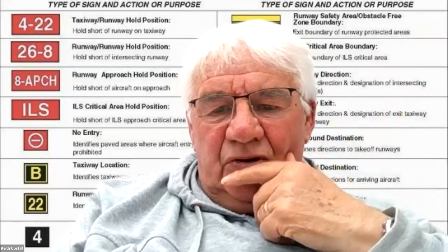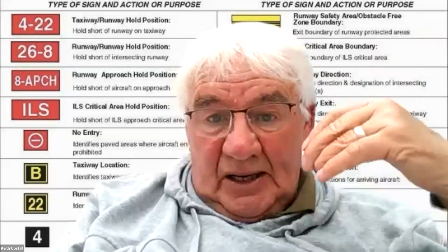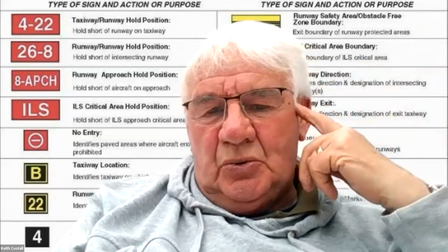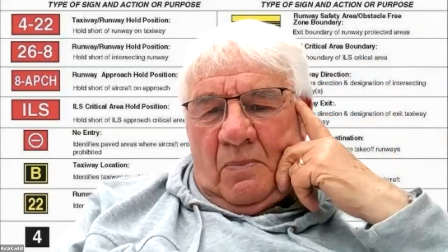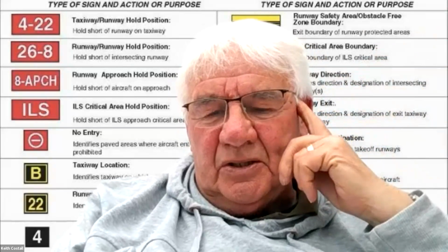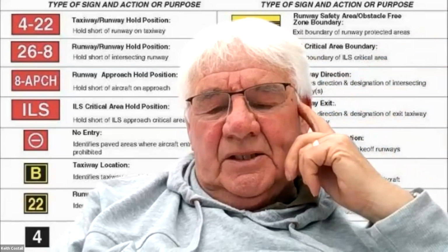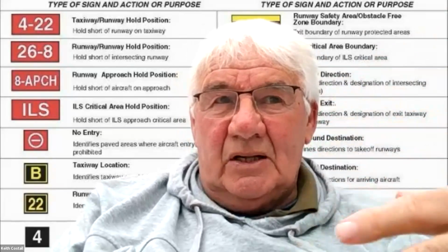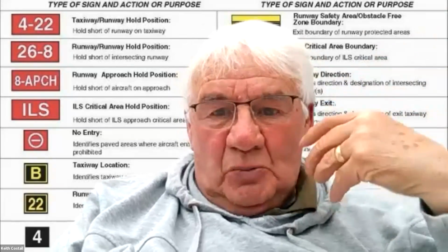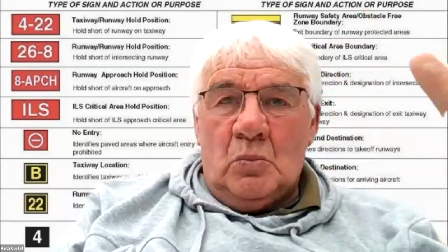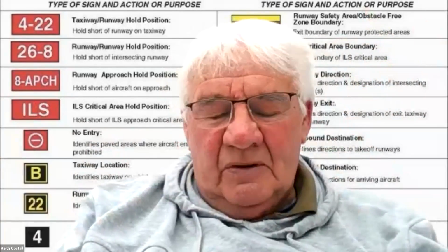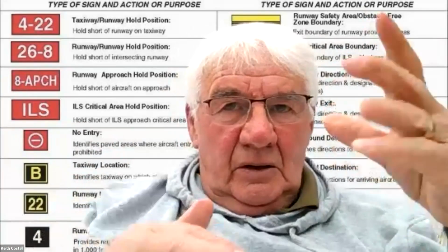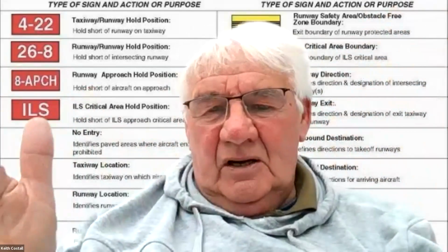When we're looking at insulation resistance values and the guidance on allowable earth leakage, which is defined as 2 microamps per transformer and 1 microamp per 100 meters of primary cable, when we do the mathematical calculations using Ohm's law, we get figures somewhere in the region, depending on the length and the number of lights, of 20, 30 to 50 megohms.